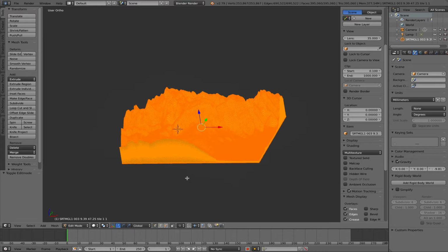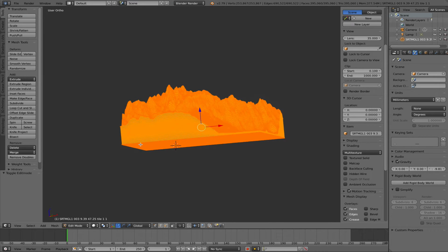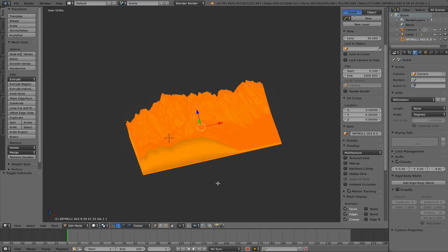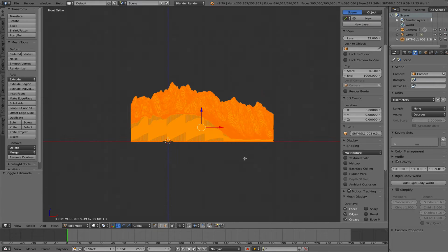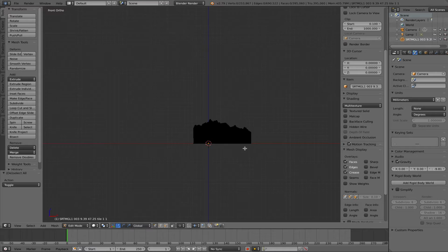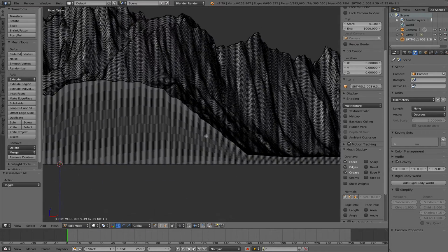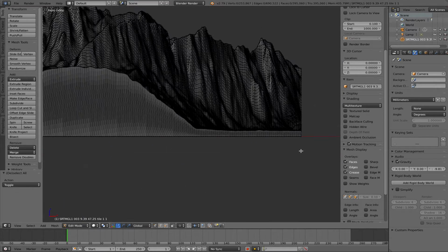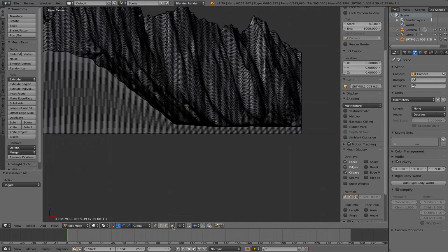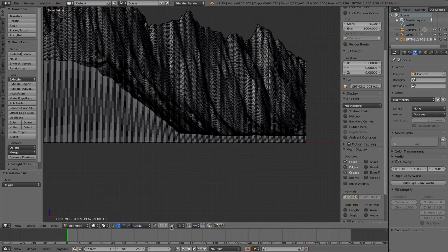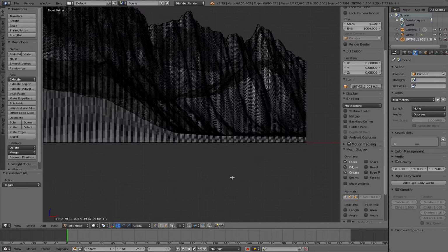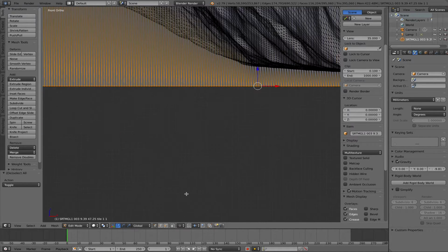So the first thing that I want to do, I don't really want that box nature from InstantMeshes. So I'm just going to simply delete. First of all, I change this to through select. It's similar to what you do in Fusion 360. And hit the B key and box select all the vertices here on the bottom.